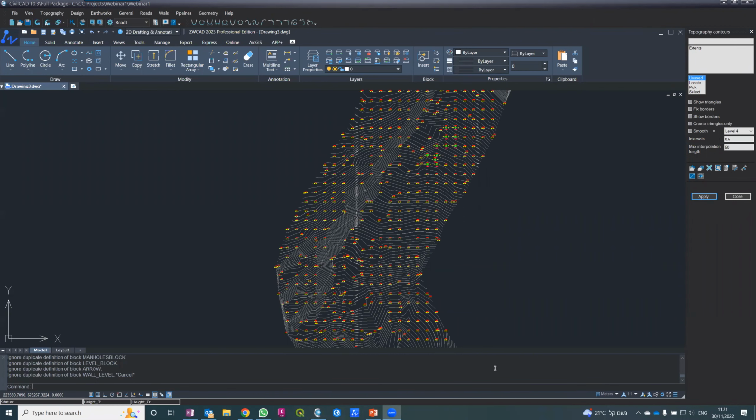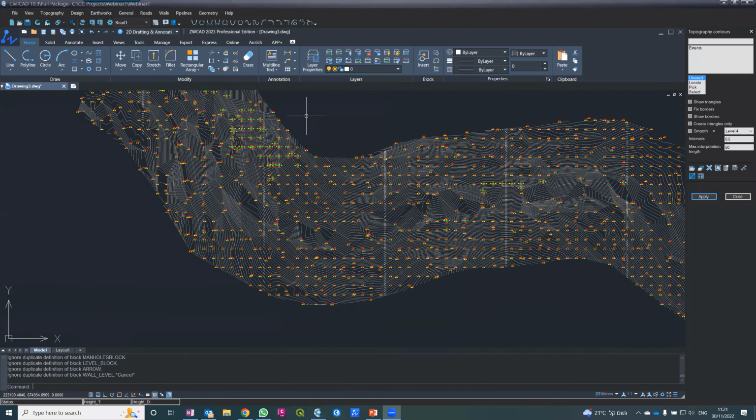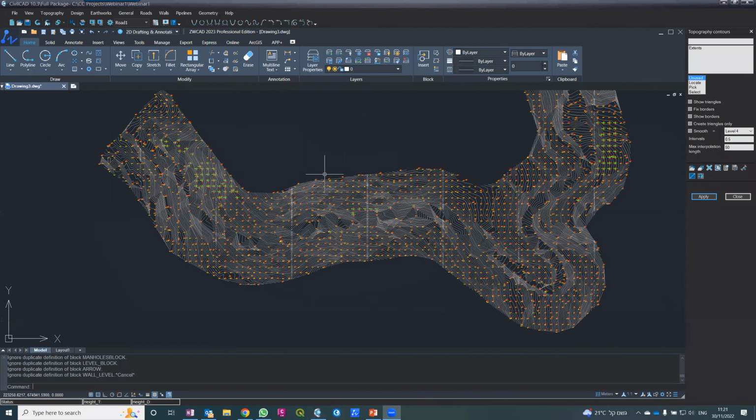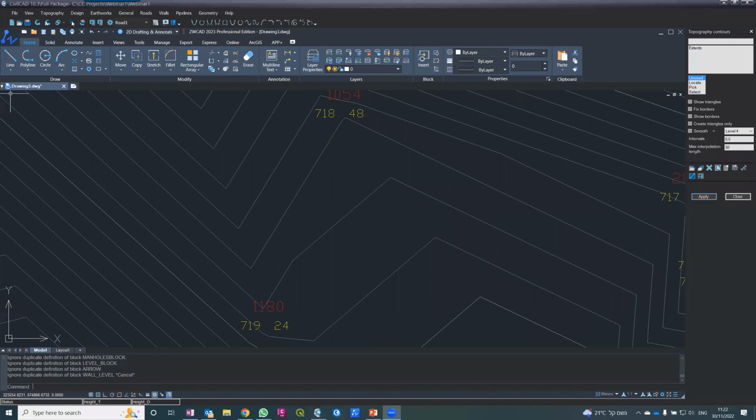Okay. So I hope you can follow what I'm demonstrating, but we received contour lines. Unless you have questions or you want me to repeat it, the good thing is not just that I have contour lines, I also have a 3D surface. What does it mean? It means that if I click this button here, for example, and pick here, or here, or here, I see the elevation below. It says height. Wherever I click, I get the 3D elevation at that location. Right, so I have a 3D surface.